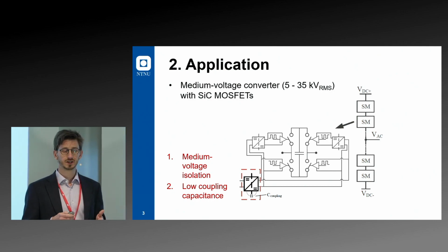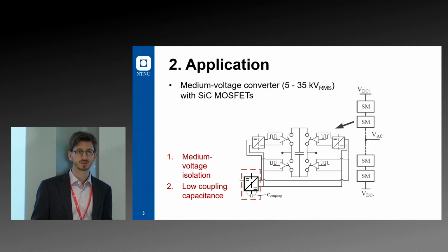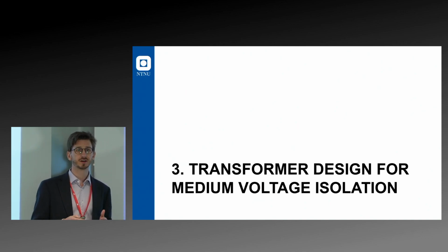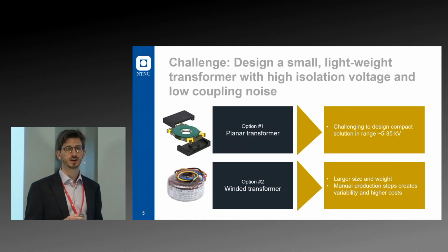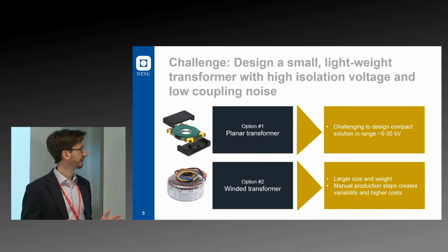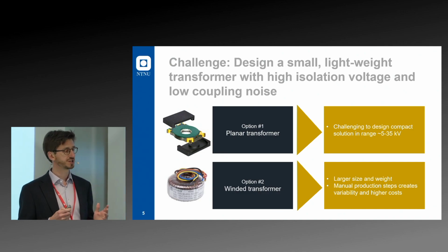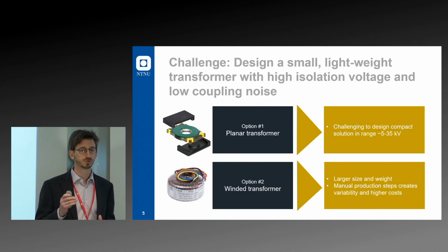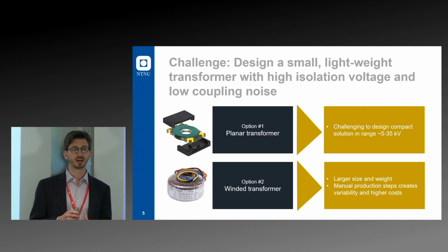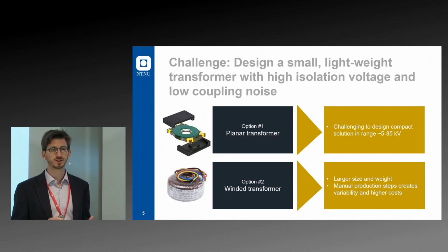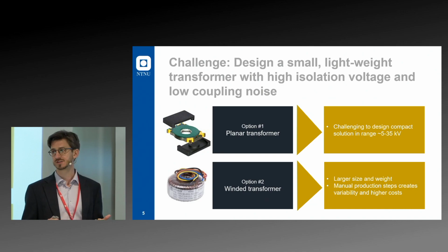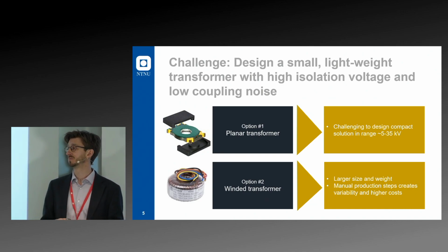So to do this, we chose a magnetic transformer. You can do it in many different ways, but this was our choice. We could go for a planar option, which becomes challenging to design when you go to these high voltage levels for the dielectric design, or the more traditional wound option gives a larger size and weight and includes manual production steps.